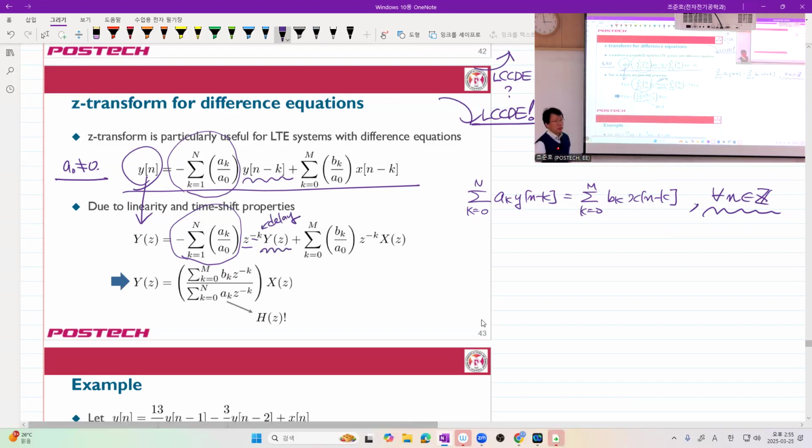And the original Z transform. Now, what about these things? You have the same summation and coefficient. And here you have the delayed version of the input, delayed by K. So Z to the negative delay. Again, this one and that. And what do you do? You collect these terms and group them together. And so actually, you can directly do this. I prefer that one.